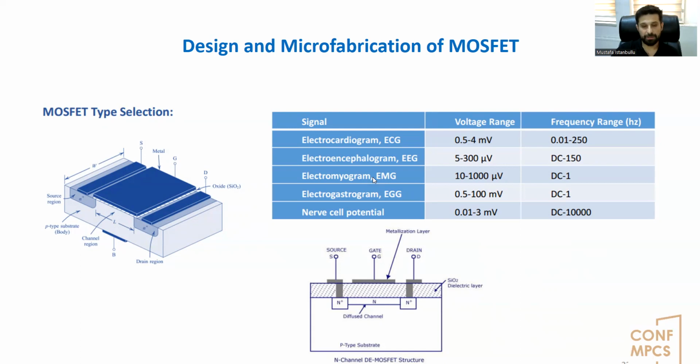For this reason, a depletion type MOSFET is selected to fulfill these requirements, because the depletion type MOSFET has a built-in channel region, so it continuously operates in on state. Therefore, if the drain terminal is positively charged with respect to the source terminal, the current flows between source and drain, even if a positive voltage is not applied to the gate terminal.